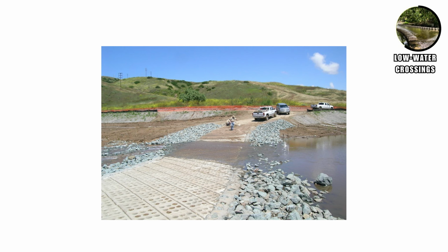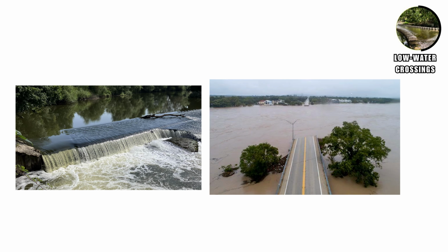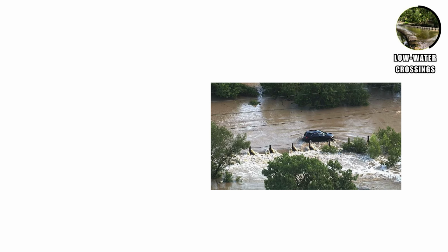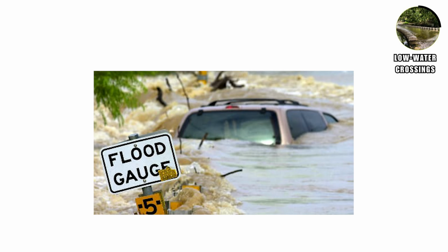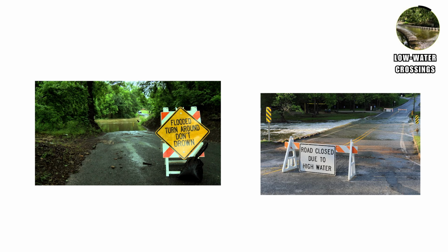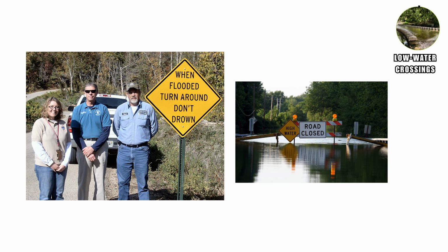Low water crossings have disadvantages. They can block fish passage like a dam, and there's safety. A significant proportion of flood-related fatalities occur when someone tries driving through water overtopping a roadway. Water is heavy, and it takes only a small but swift flow to push a vehicle down into a river, which means resources saved by avoiding the cost of a higher bridge are often spent erecting barricades during storms, installing automatic flood warning systems, and running advertisement campaigns encouraging motorists never to drive through water overtopping a roadway.